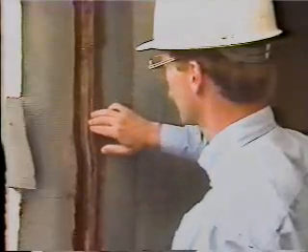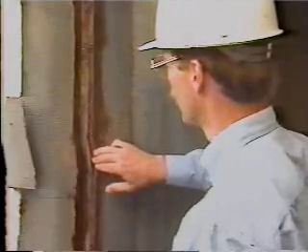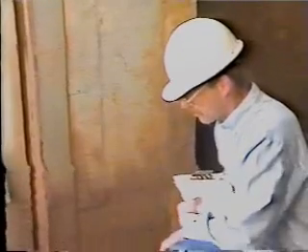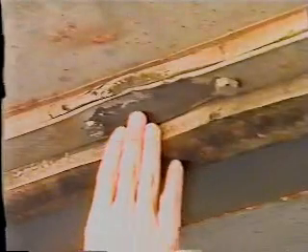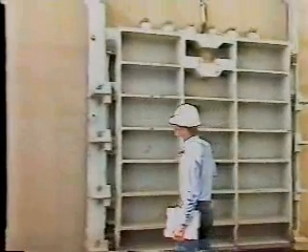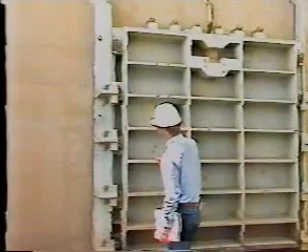Look at the seals and seats for signs of cracking or other damage. On the upstream side, look for damage to the walls and area around the gate opening, especially in the lower corners. Look for debris. Debris can damage the seal and stop the slide gate from sealing properly. Check the upstream surface of the gate leaf for damage.